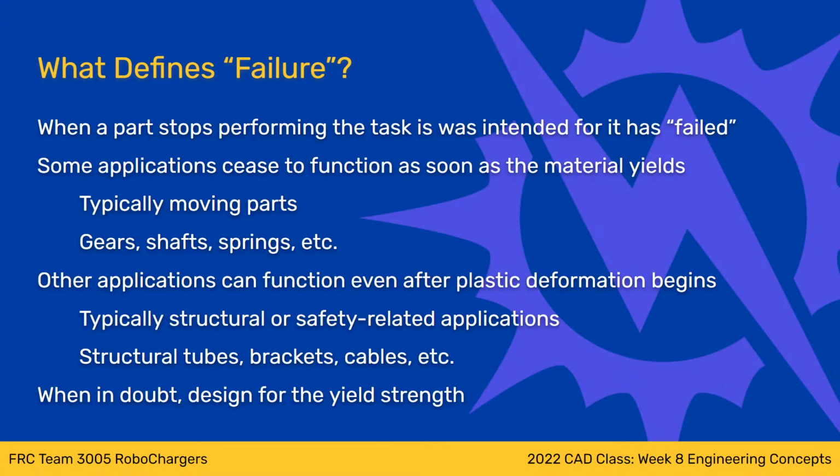So if you think about, I don't know, a cable on a crane or something. If that cable gets overloaded for some reason, you really don't want it to just snap and drop whatever it is that the cable is holding, right? You're okay if that cable stretches a little bit. You will not drop a large piece of concrete on somebody's head because the cable on your crane stretches and undergoes plastic deformation.